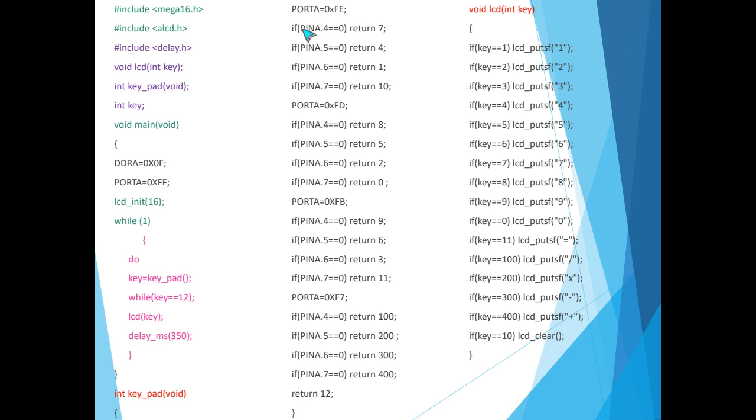semicolon. If PINA.4 equals 0, return 7. If PINA, what do we mean by the PINA register? Do you remember? What is the meaning of the PINA register? We said that we want to scan the keys of the keypad, and to do that, we need to read the state of the registers, the data of the pins.